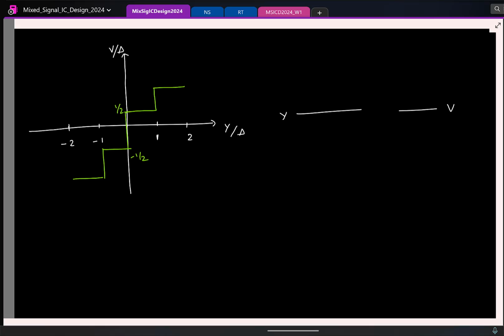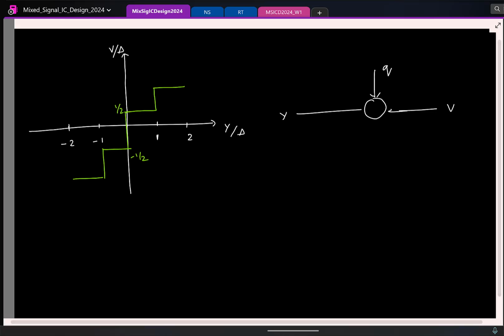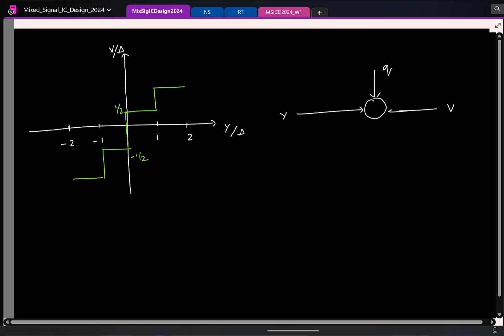I mean, if I have to model this operation mathematically, using an offset and a scaling factor. So yeah, what you say, you can just add something here. See, quantization is rounding off. You add something here, that is the appropriate error that you are incurring in the quantization process, to get the output. Okay. I mean, that's what I meant by model. So here Q is what we call the quantization error. Again, it's a matter of fact naming.